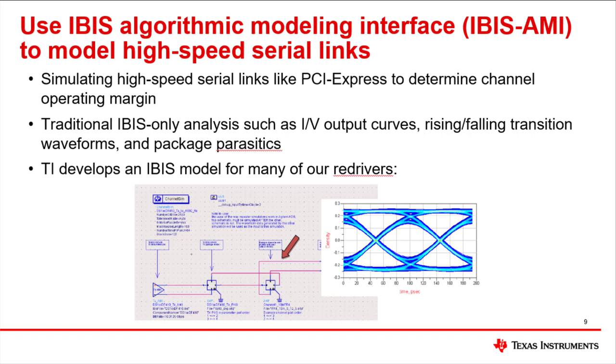Additionally, once you are certain of your system loss, you can leverage IBIS AMI models developed by TI to perform simulations on high-speed serial links. Many of our redrivers have IBIS AMI models pre-created that can be used to provide current voltage output curves, rising-falling transition waveforms, and see package parasitics. With an IBIS AMI model, it is a lot easier to determine whether our redriver will be able to compensate for the loss in your system. So, it is recommended to simulate before you design.